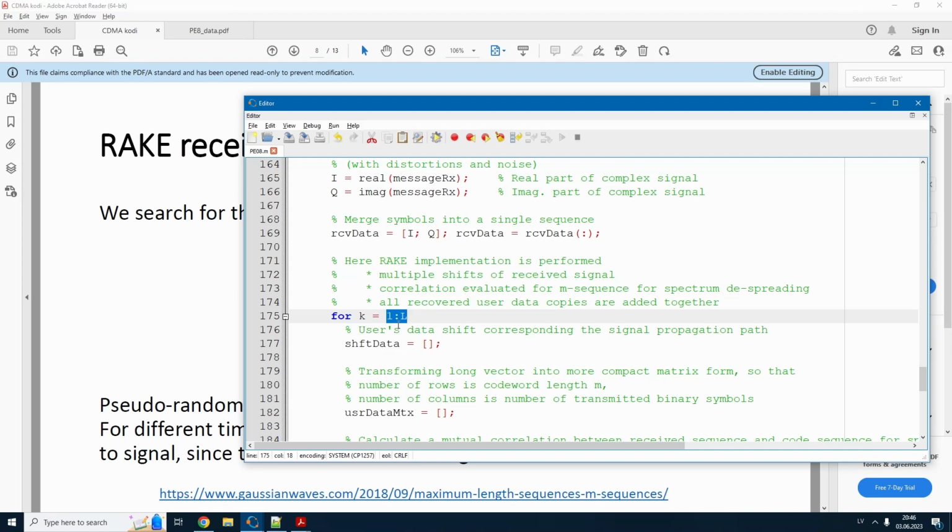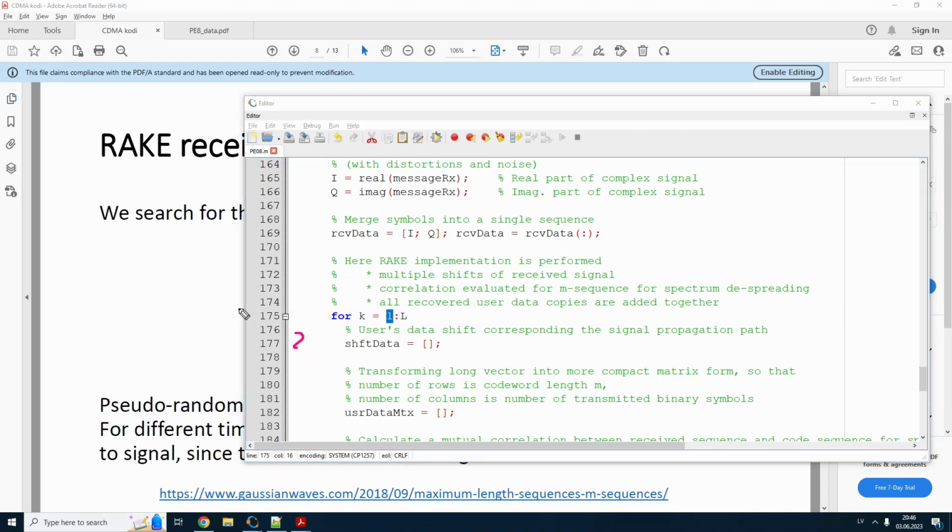For the first element we don't need any shift. For the second we need to shift by 2 positions, because in our received data we have, say, +1 -1, which together in QPSK was one QPSK symbol. So we have to shift by QPSK symbols: first QPSK symbol, second QPSK symbol, third. So the step of our shift should be 2 in this particular case.